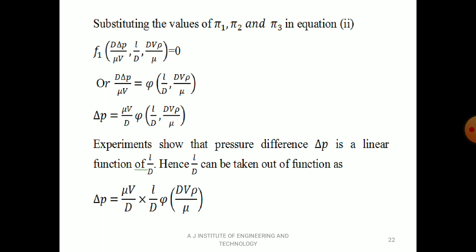Then turbulent flow and viscous flow. Viscosity you have to remember: instead of rho, as rho value is given in the problem, don't get confused. Don't take rho as repeating variable. So viscosity means it is due to viscous force. So you have to take mu as repeating variable in place of rho. Whereas in turbulent flow, even though mu value is given, you have to take rho as repeating variable. So that's the conclusion from these three problems.